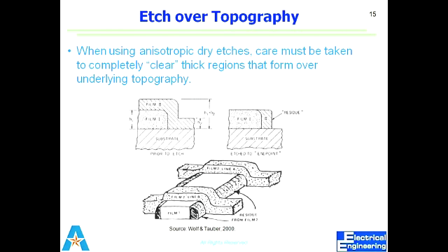Okay, so this slide talks about the over-etching process, and why in certain cases we go for it. You can see in the figure that if you have directional etching, and in this part the film thickness is high. If I had directional etching, I know the etch rate, and I have decided on the time I should etch for. In that case there would be some residue of the film that needs to be removed.